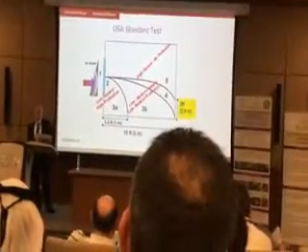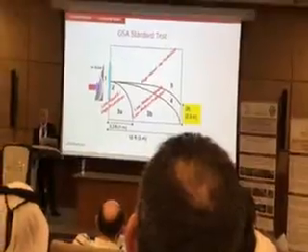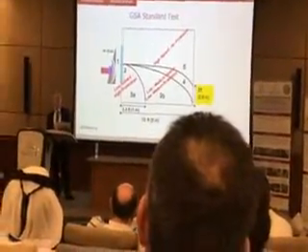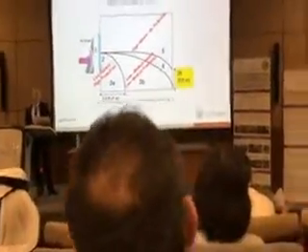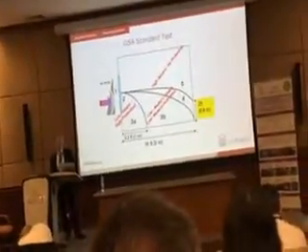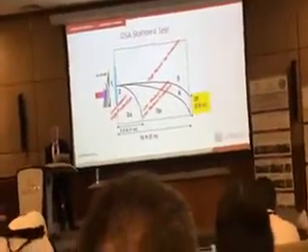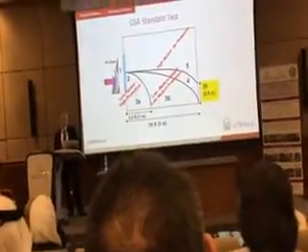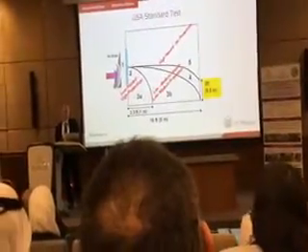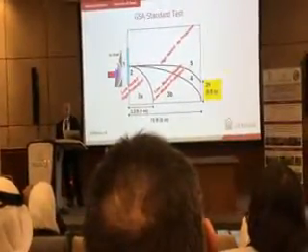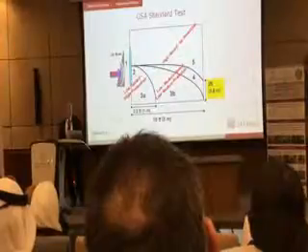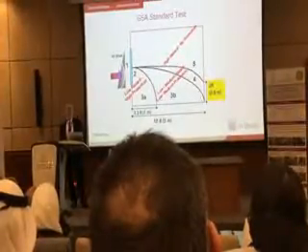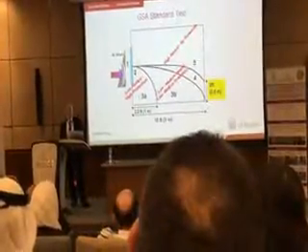They have a test. So this test involves applying either 4 psi or 10 psi pressure on a window, and if fragments fall within 1 meter, it is a very low hazard or high protection window. If the fragments go all the way to 3 meters, then it is low to medium.